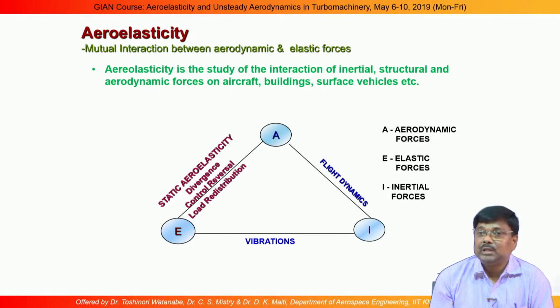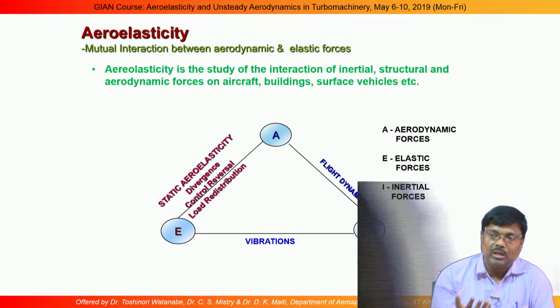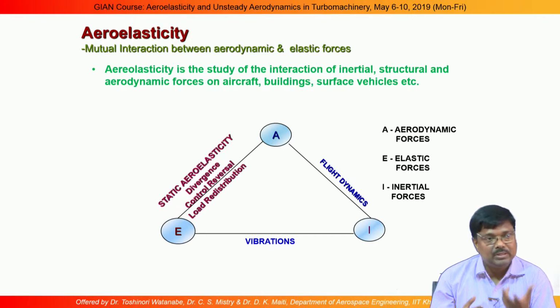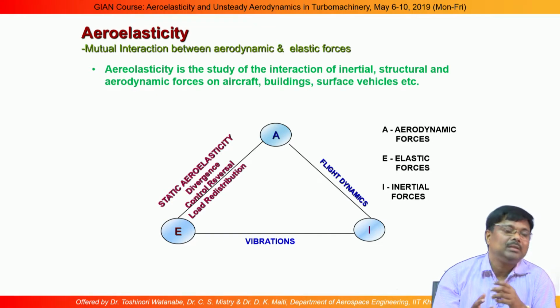The aircraft may achieve a velocity such that the moment acting on the control surface, which is mounted on a control mechanism with a particular stiffness, balances it. When this aerodynamic moment and the control stiffness are balanced, we call the situation control reversal.